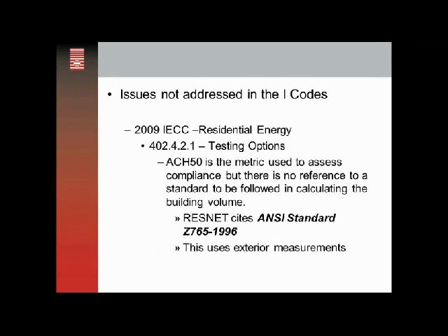Historically, with envelope testers, there's quite a history of having the metrics change on us. Old timers are quite familiar with just coming in and doing single point testing for CFM at 50, and then having to interpret those results for homeowners. The issue with that was that it's a very raw number. It's not normalized for either square footage of conditioned space, square foot of surface area of envelope, or a volume-based metric like air changes at 50.